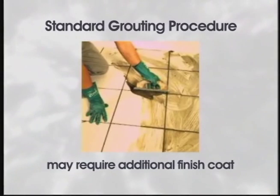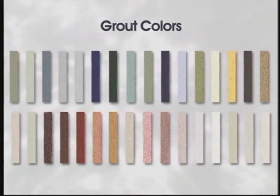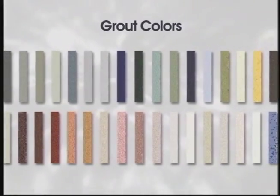A standard grouting procedure can also be used. This may require an additional top or seal coat to hide scratches or blemishes which might have occurred during grout application. Grouts come in many standard and custom colors. Use these to add highlights to your design.